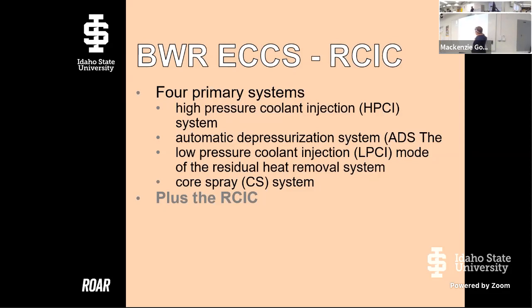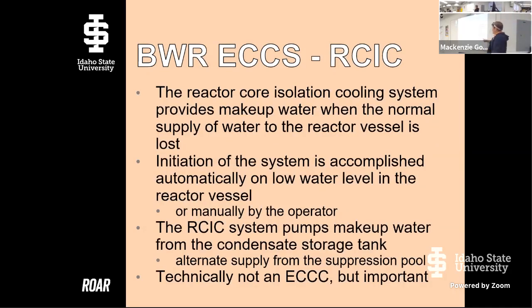BWR has a high pressure coolant injection system, just like a pressurized water reactor. It has an automatic depressurization system. It has a low pressure coolant injection mode, and it has a core spray system. And then you have your reactor core isolation cooling system, okay?